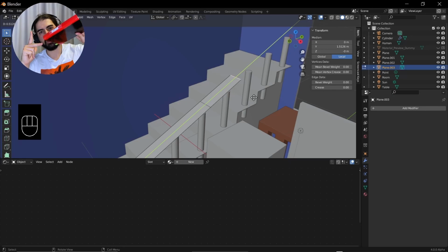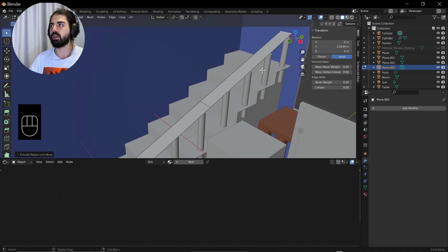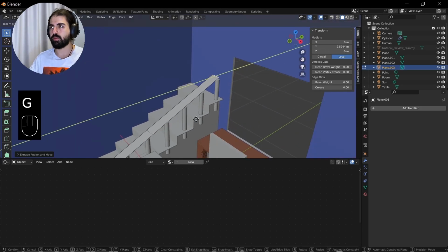But if you move the object's coordinate or location will change with it. So let's say you turn it, then it will also turn the coordinate system. If you press Y twice, you will use the Y coordinate of your object, and this is why we can extrude it along this face for now.